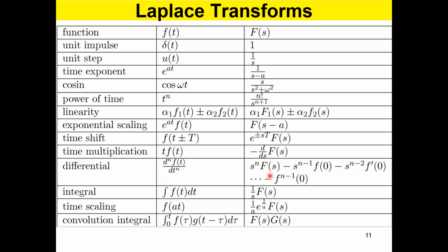And it has the Laplace itself, that is F(s). But in addition to that, you have f(0). f(0) means the time 0 position, the variable at time 0 in time domain. And also f dash (0), that is the speed or the first derivative of whatever that variable is in time domain. So these are time domain values of the function. You just figure that out, but at time 0, what is f dash, and bring it over here. And in Laplace representation, we don't have anything other than F(s), right? We don't have f dashes or integration of s. That is the beauty of going to Laplace.